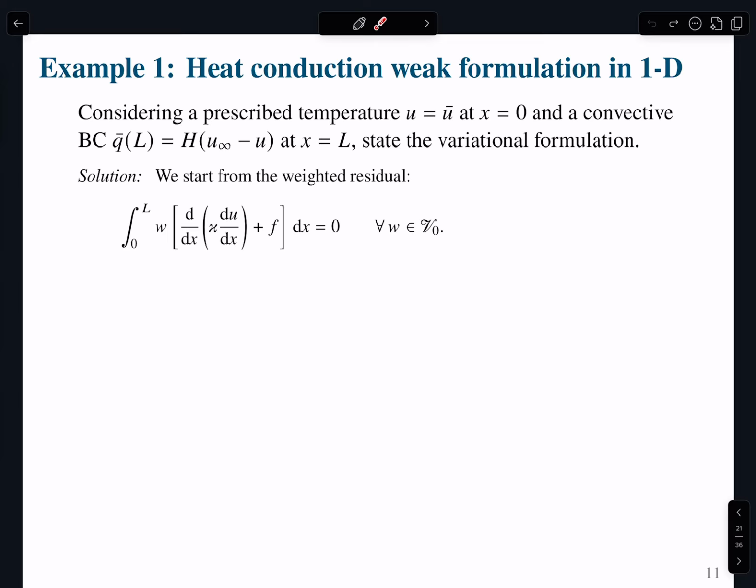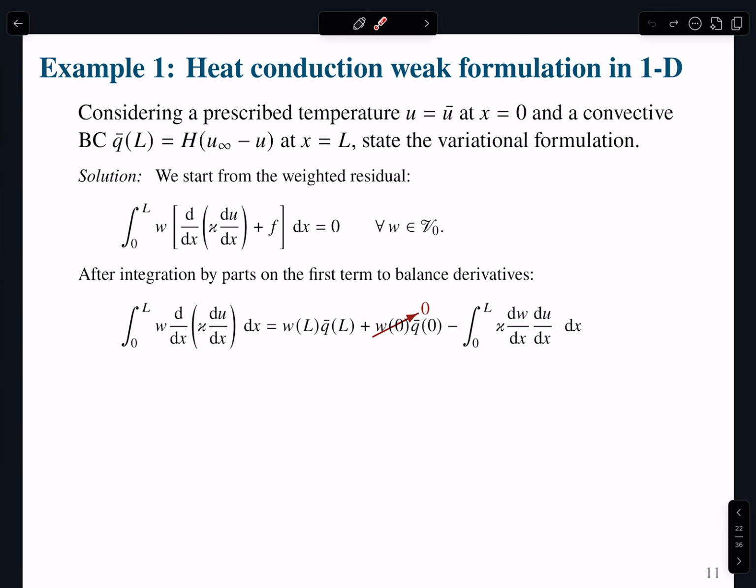Okay, so again, we're going to take our differential equation and multiply by a test function. Remember, this is our projection statement. These are, again, to me, the best invention in mechanics. The projection is like crazy. Remember, we're going from infinite dimensions to a finite dimension. Not yet, this is still infinite dimensional. But this projection is crazy, saying that my differential equation has to be orthogonal in the sense of the bilinear form to my test function. It is insane. These orthogonality conditions are, again, a really great invention.